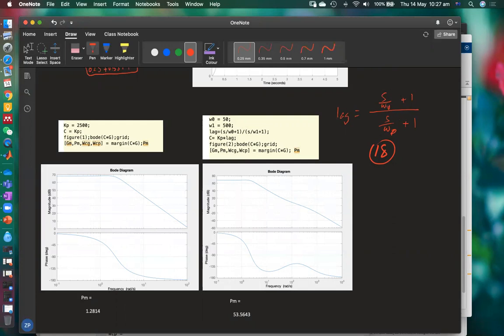If this omega 0 is less than omega p, you will have a Bode diagram like this, let me see, it goes to 0 earlier. So the system will be like this. That's your gain, this is your magnitude. And your phase will look like this: it goes down, then goes up.